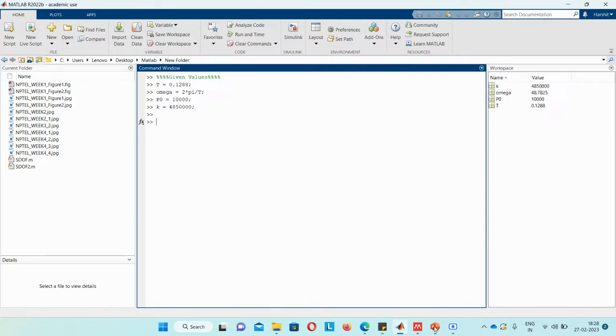Okay. Now, the second step is to define the time related parameters. What parameters are there in this? The observational range, for how much time we need to observe. So let's observe the response for 10 seconds. And what is the least count we can keep? Let's keep the least count of 0.001 seconds. So after every 0.001 seconds we will get a value, and this will continue till 10 seconds. So we'll get a large number of values, and when we plot the data, we'll get a very proper smooth curve. This is the range in which we will study.